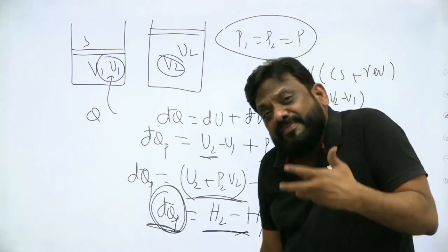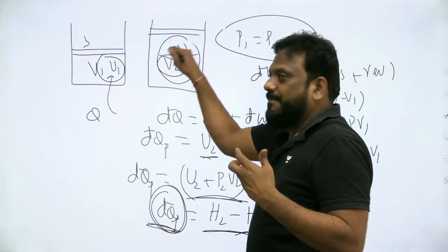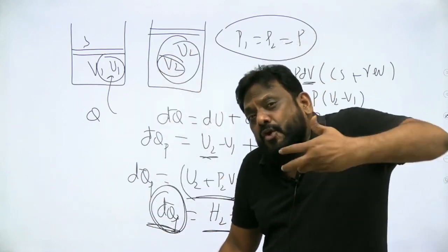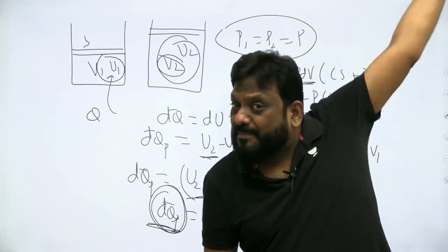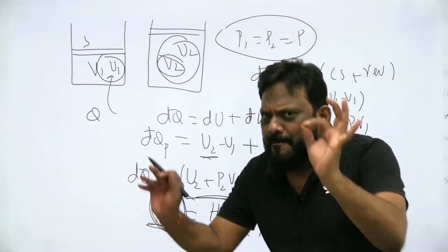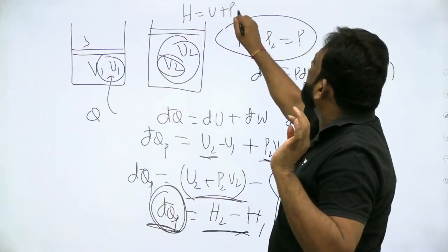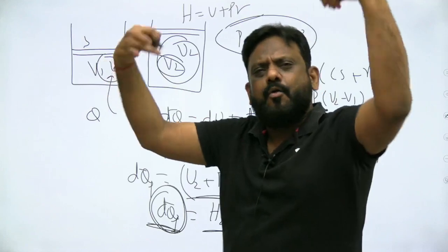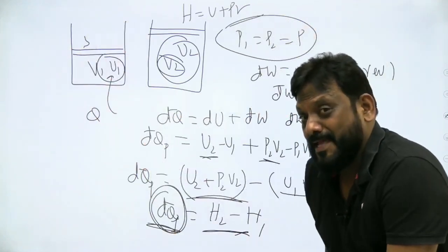But it means when they use the word heat content, they are referring to a closed system. When they say microscopic form of energy of flowing fluid, they mean that it is applicable for flowing systems, open systems. So don't get confused, sir. My mathematical formula remains the same, that is U plus PV. There is no change. So now, again one student asked me a question.